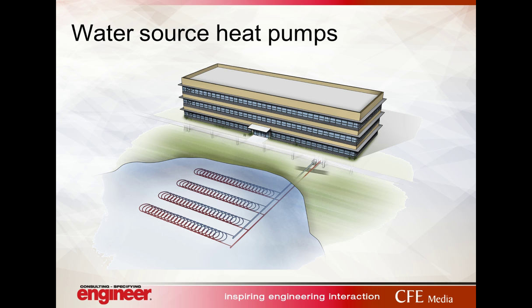Water source heat pumps are typically zone-based water-cooled DX systems that share a common condenser water loop. Now, these actually a lot of times are above the ceiling in spaces. Then they'll have ventilation brought directly to them. So generally these are coupled with a dedicated outdoor air system, which is a very efficient way of providing ventilation to your zones. This allows for an increased efficiency through greater zone control, higher water-cooled efficiencies, and there's heat sharing through that common condenser water loop.